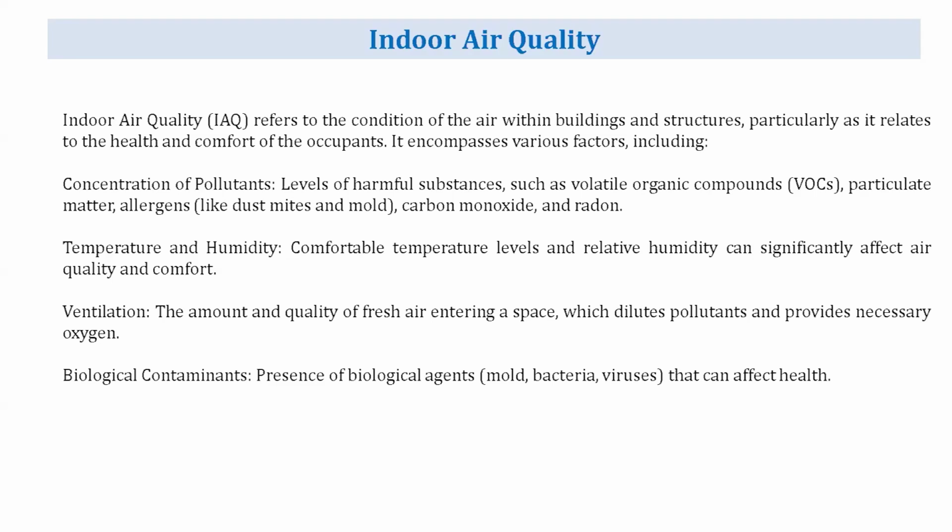And relative humidity should be somewhere around 30% to 50%. Less is also bad because the air becomes dry, and then you have a lot of problems. And more humidity is also a cause of problems. So the ideal range of humidity indoors is somewhere around 30% to 50%.